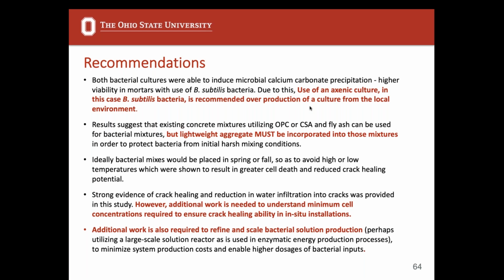You're essentially feeding the bacteria, and since the crack has happened, that's opened them up to oxygen as well. So they're breathing, they're getting the curing solution, that's enabling them to precipitate. I would say that you should stop spraying the curing solution once you see crack healing, or if after 4 or 6 weeks you don't see any crack healing, it's possible that the bacteria may be dead and not working. So you don't have to spray curing solution for the entire life of the bacteria. You just begin spraying it when the crack happens, and you can stop spraying it when you're happy with the amount of precipitation that's occurred within that crack.